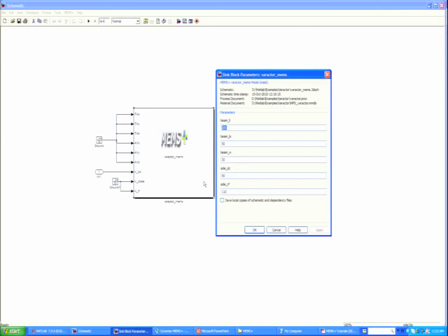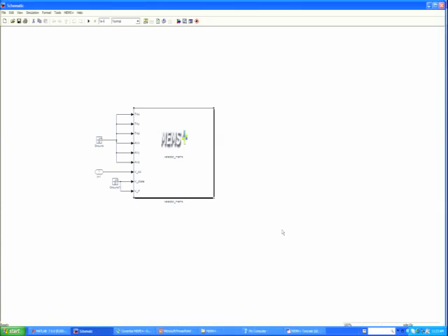If I do want to change a beam and it's not described here, I have to go back and do it. But now I'm all ready. So Steve mentioned earlier the three things I'm going to run: first an AC analysis, a frequency response analysis. Second is a DC analysis, where I'm going to sweep the voltage on this thing to try and find pull-in. At what point does it snap down and make contact with the bottom? And third, I'm going to run a transient, where I'm going to put a voltage pulse on one of these pins. I think it's the VRF or the V plate, I don't know. I'm going to disturb it with the voltage and release it so it bounces around. Okay, three results.